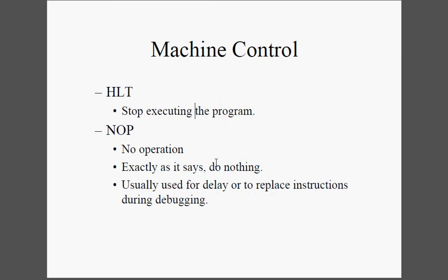This is the machine control. For example, the HLT, which will tell the microprocessor to stop executing the program, meaning done, stop, don't do anything. And this is no operation, which just does nothing. Normally it is used for delay purposes.